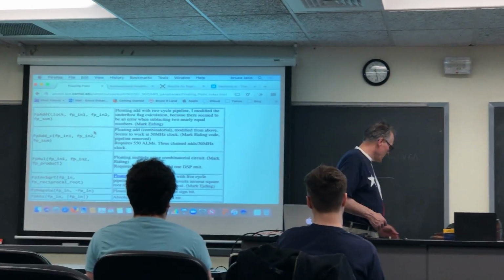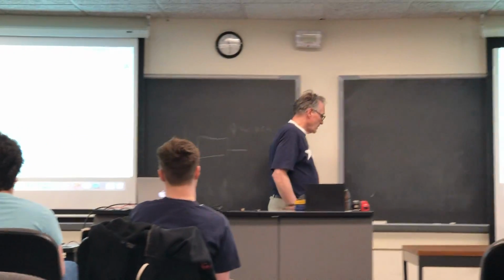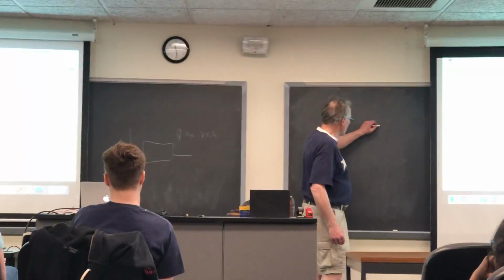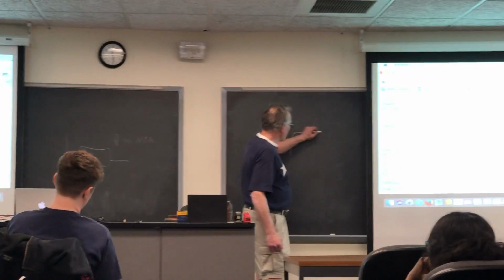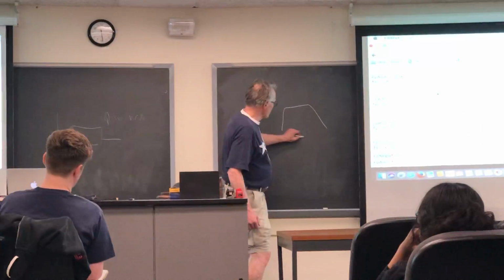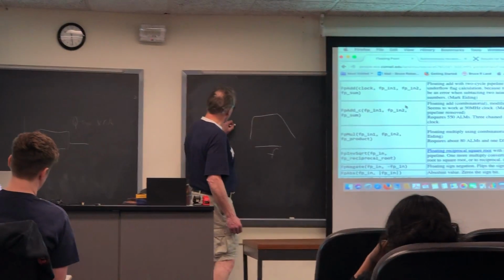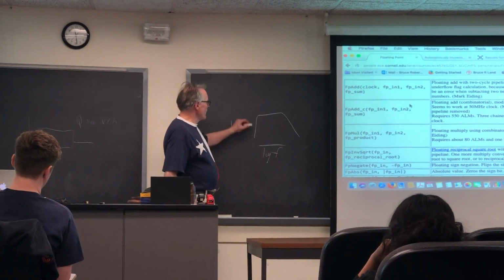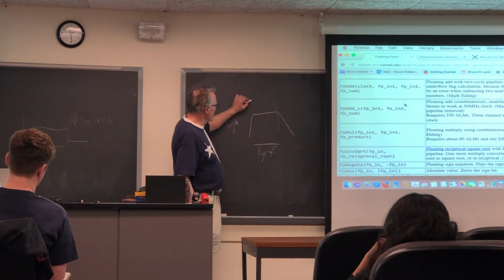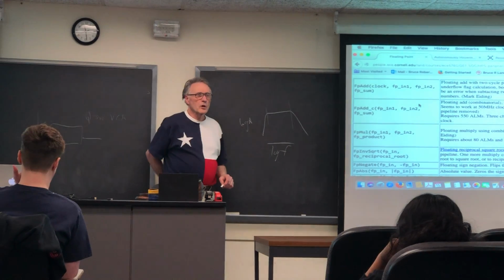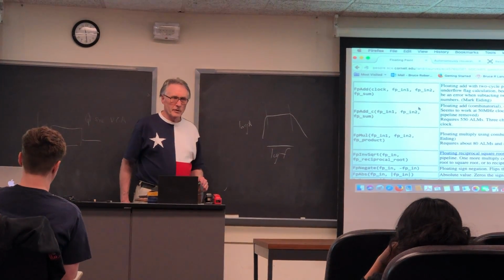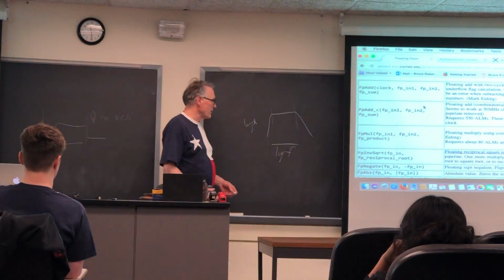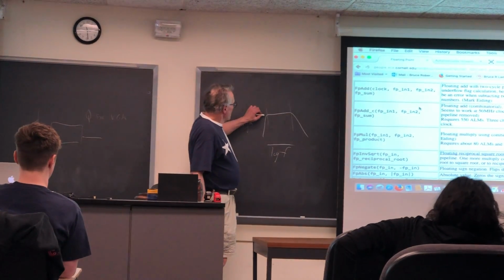Okay. So, let's say that you want to make a sharp cutoff infinite impulse response filter where frequency is this way and log amplitude is this way, then to get sharp cutoff, you have to have a large number of poles in the filter, right? RC sections, however you want to think of it.